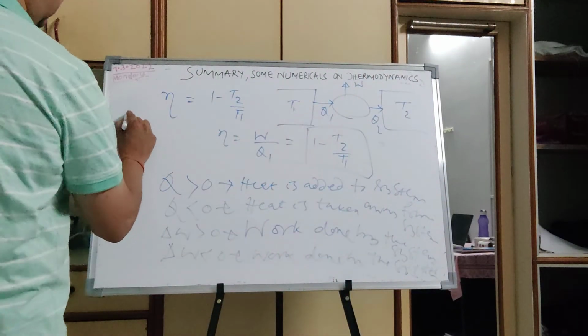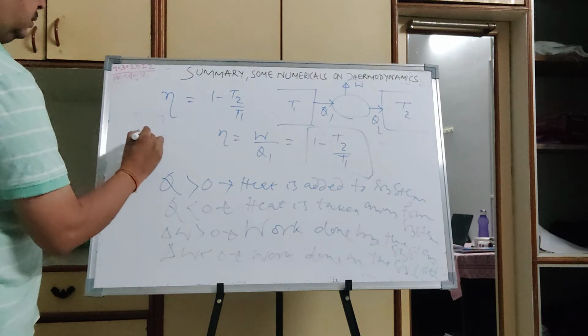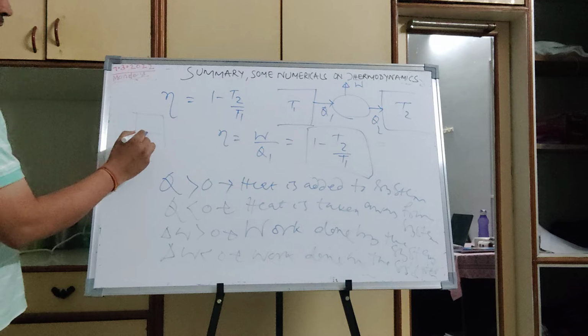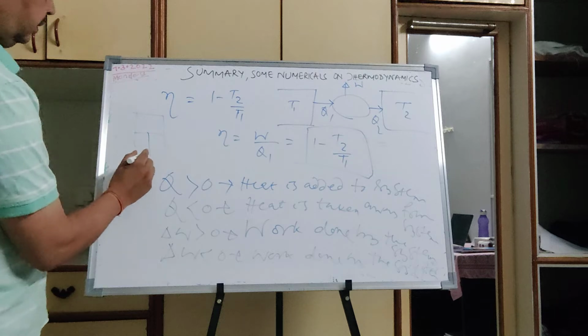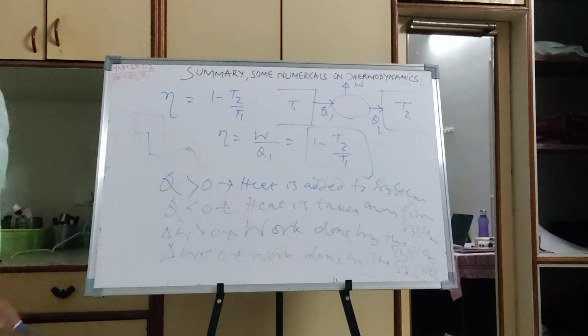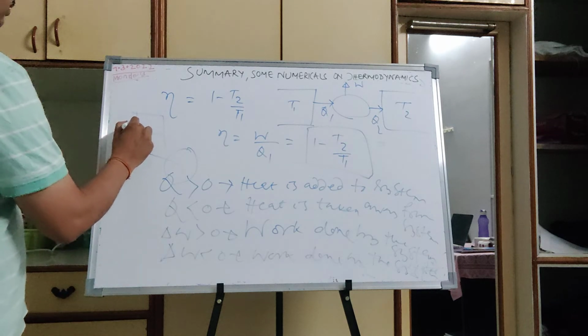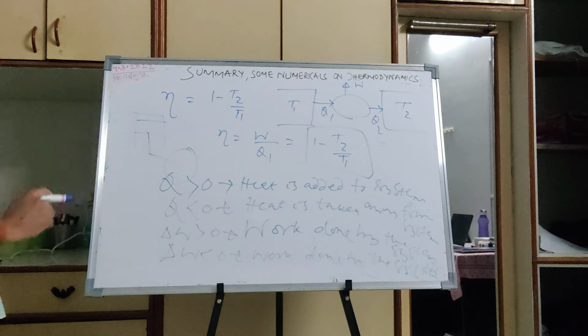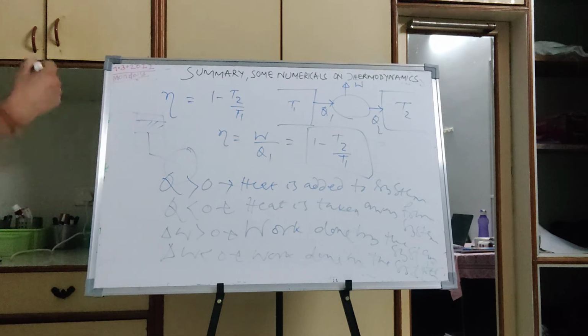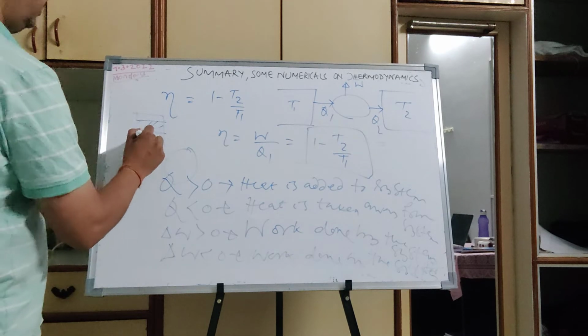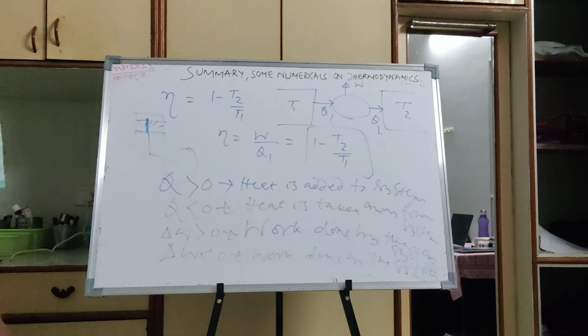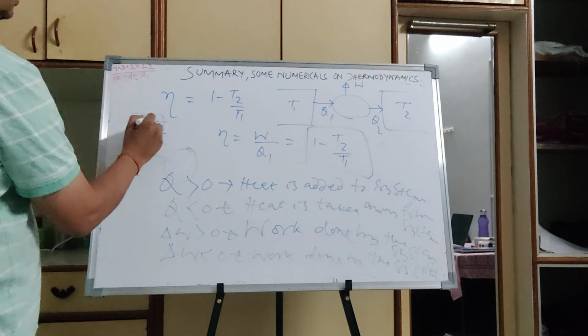So, I was telling you, you have a piston cylinder arrangement. When this piston is moving forward and backward, it is connected to a connecting rod, then to your shaft, and in turn connected to the wheel. When it gets expanded, it does work. From here to here is the stroke length of your engine, and there will be some clearance volume.